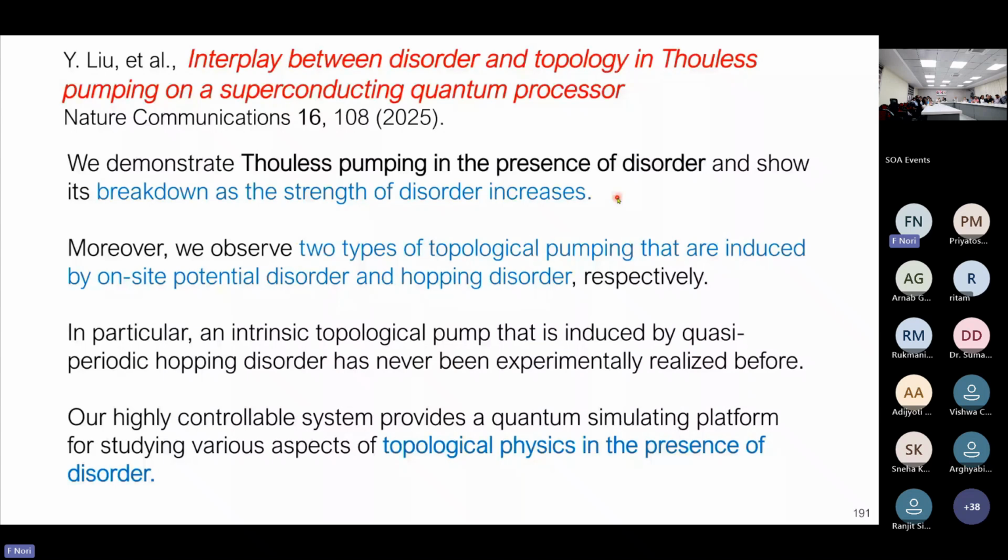Thank you. Okay, for the first question, yes, you can tune in principle the resonator or the qubit. It's simpler to tune the qubit, so that's a matter of simplicity, but both can be done. We have a theory and experiment where the resonators are tuned like a trombone, that can be done. But this gives simplicity. Question number two, yes, the mechanical resonators couple to the substrate. The substrate is gallium arsenide that can have surface acoustic waves, and then the electrical signal is piezoelectric. It propagates, and it actually can excite the atom. This has been done both ways: the capacitor exciting the qubit, or the qubit sending a signal to the capacitor. So both can be done.